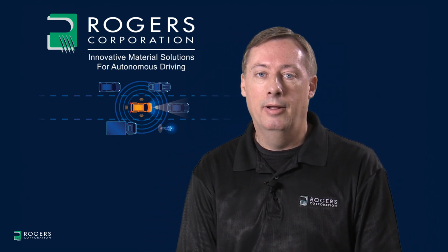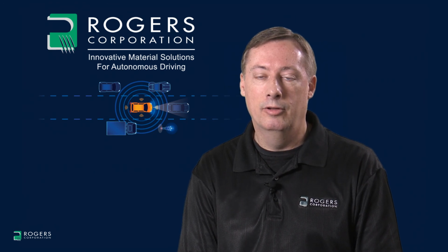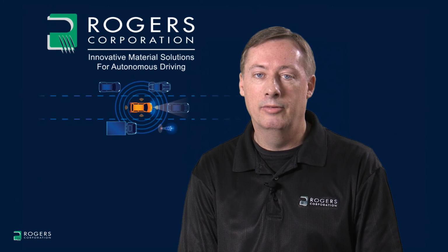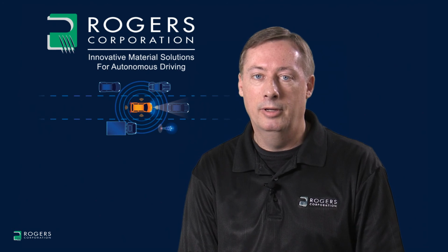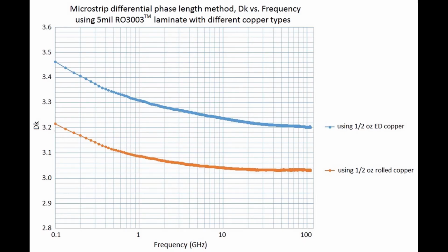In the following chart, I show the effects of copper surface roughness of 2 different types of copper used on 5 mil RO3003, which is the material predominantly used in the 77 gigahertz automotive radar sensor applications. The chart shown here is the dielectric constant versus frequency chart for 5 mil RO3003. However, it's using 2 different coppers. The blue curve shows circuits using the standard ED copper, which is very commonly used in the 77 gigahertz automotive industry right now. The orange curve is the same circuits except using rolled copper, which is very smooth. Rolled copper has a surface roughness of about 0.4 microns RMS. The ED copper has about 2.0 microns RMS.